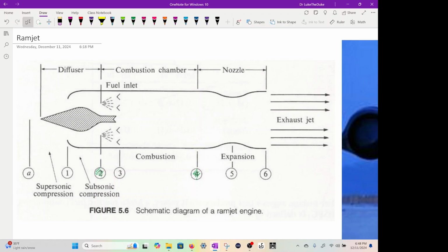Okay, so here is the schematic. It's a side profile of a ramjet. And ramjets depend on ram pressure. So you have to take these off by some sort of mother plane, catapult, or other powered flight to get them up to a speed, and then it will basically force the air inside, and then it will shoot out.